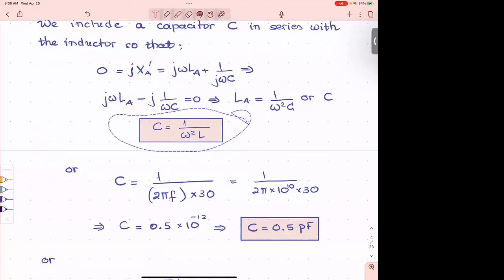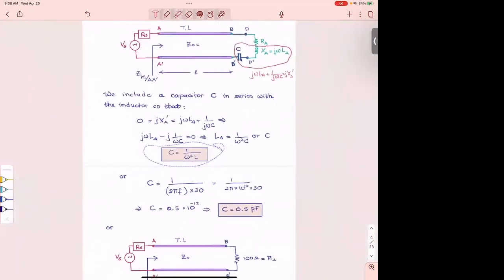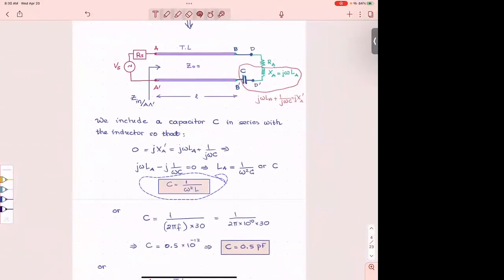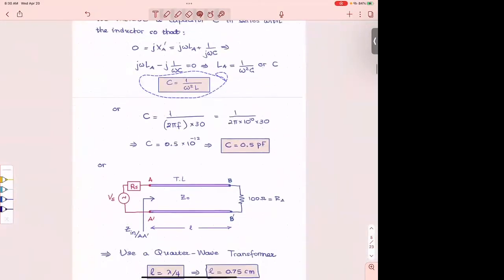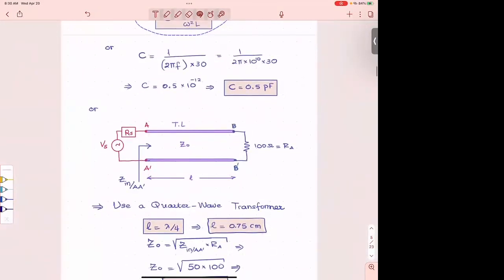So indeed, see, I have not used the Smith chart because this is easy. If I can put this C there to cancel that, then what is left is only real and is this. So what is left, therefore, is this one. So now I can use a quarter wavelength transformer, which means I can choose my length to be a quarter of a wavelength. I still can choose it. I cannot choose it not. I have to derive it, all right, from here.